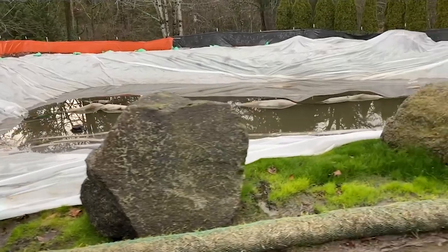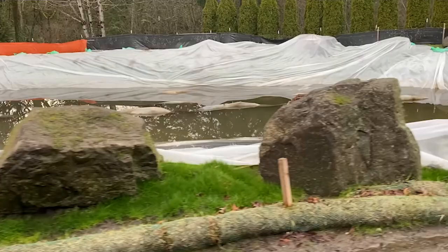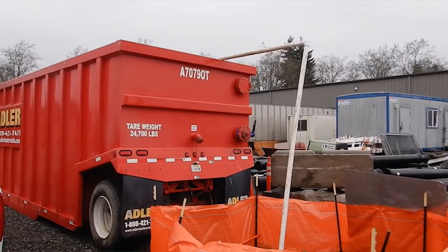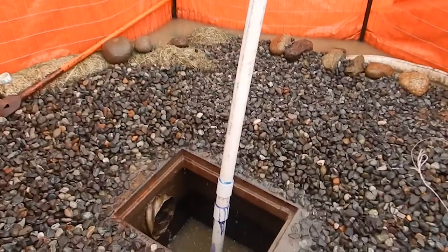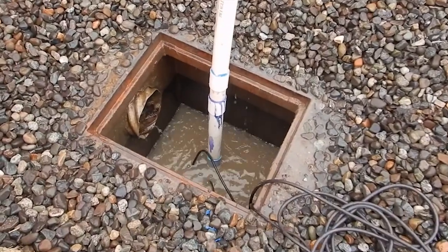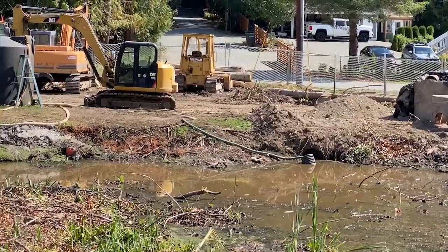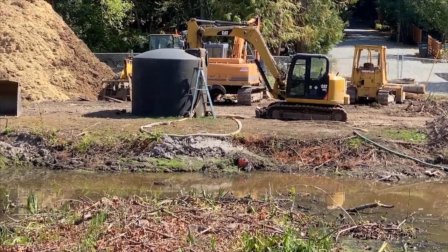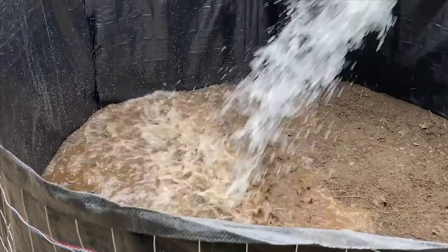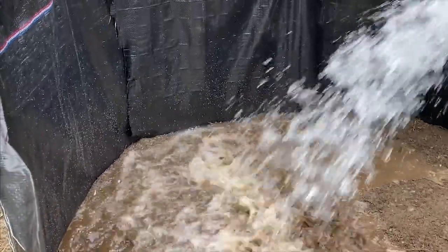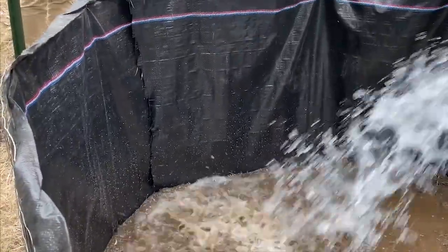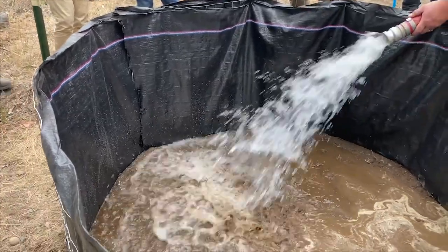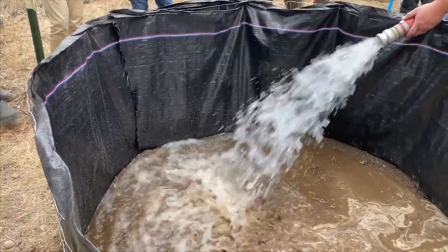Storage BMP examples are things like sediment traps or small ponds, or even tanks that you can put out there. Some tanks are pop-up tanks, some are steel, lots of different types of storage devices that are out there to do a dewatering project. We can actually create a de-water pit out of sediment fence and discharge the water as well, but you have to have a footprint for all of these storage devices dedicated for storage on your facility.